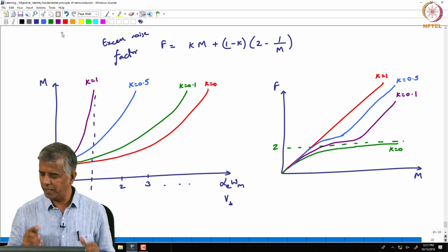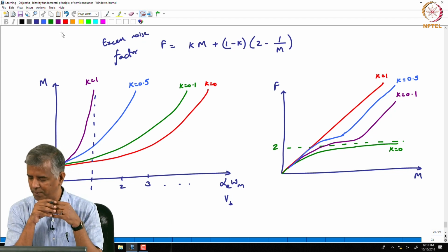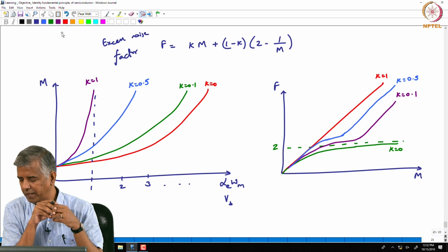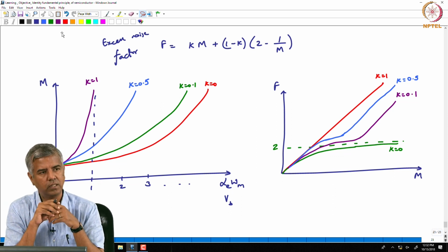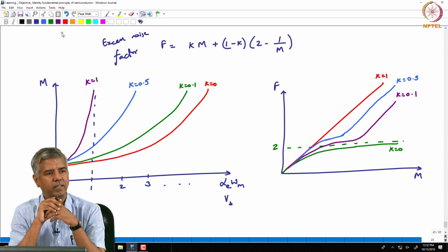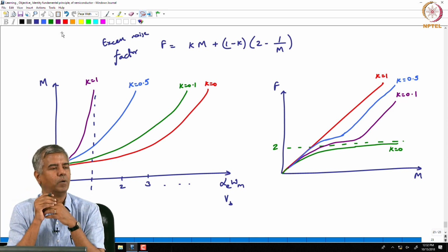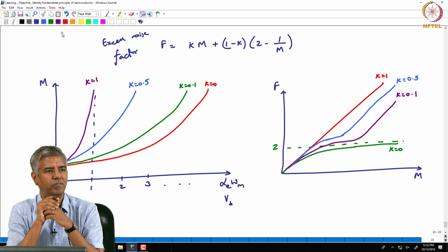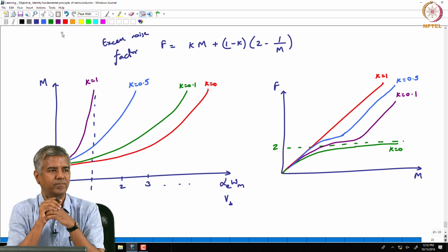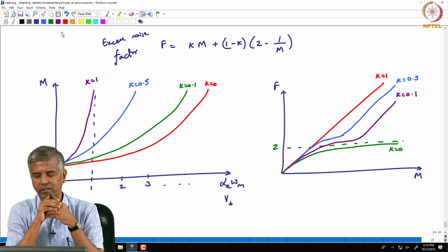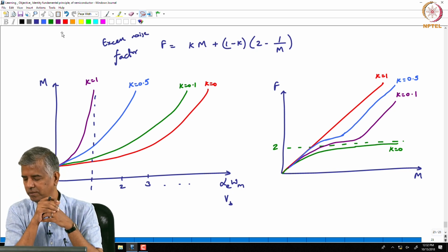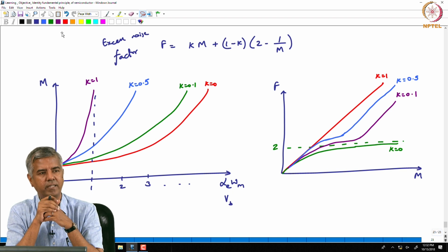If you had indium gallium arsenide and if you were to choose the best gain at which you can get the maximum signal to noise ratio, where would that point be? We are looking at that blue curve on the right graph, and we are trying to figure out where I would want to operate.